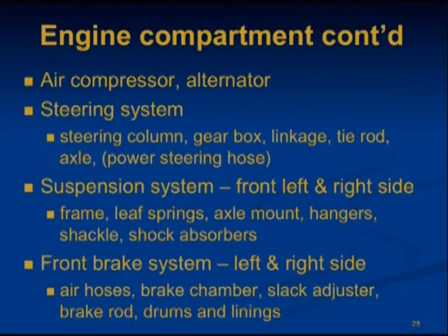Continuing in the engine compartment, check your air compressor and alternator to make sure that they're secure and not damaged and there are no loose wires. Check your steering system. The power steering hose is secure and is not leaking. The steering column, gearbox, and all the other linkage, and the tie rod from the left tire to the right tire and the steering axle are all secure, and make sure that there are no signs of leakage.